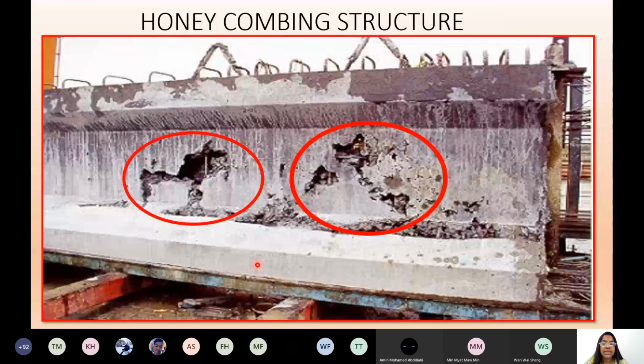Honeycombing like this. I think it's a concrete and pre-stressed concrete type. You see here the formwork has been worn out, the material itself removed. The honeycombing or a type of joint failure may be like this. It's like a small parcel of the material gone off. In the end, it will spoil the structure which is going to be built. If you build a structure, the concrete will leak through these holes, isn't it? So you need to avoid this, or fix it first and then use it.